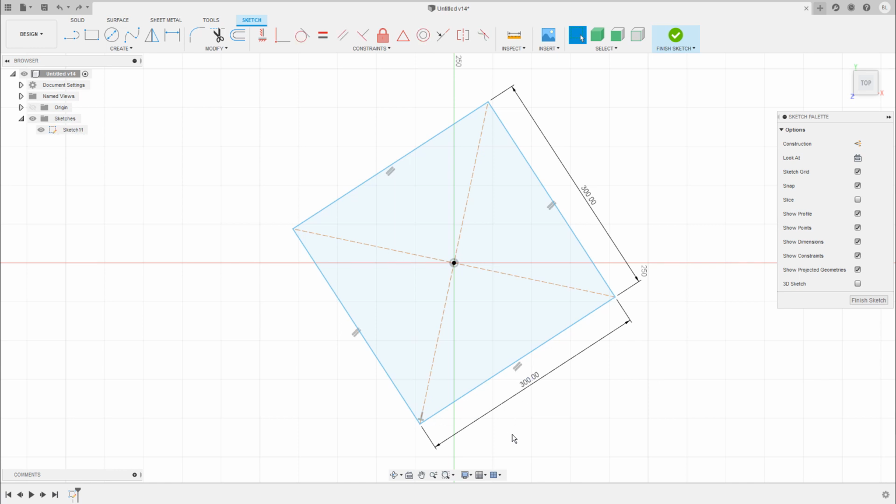In the bottom corner, you can see another constraint that looks a little bit like a reversed T. And whenever you have problems to select it because many different items are overlapping each other, simply hover over the object you would like to select, left click, keep the mouse clicked, and then you can choose from this little drop down menu what item you want to select. And in this case, I would like to select the perpendicular constraint.